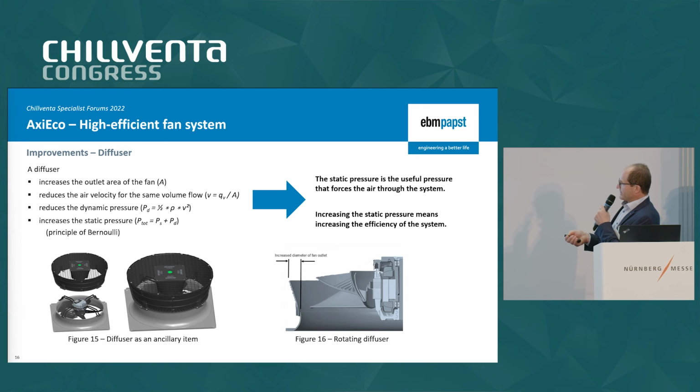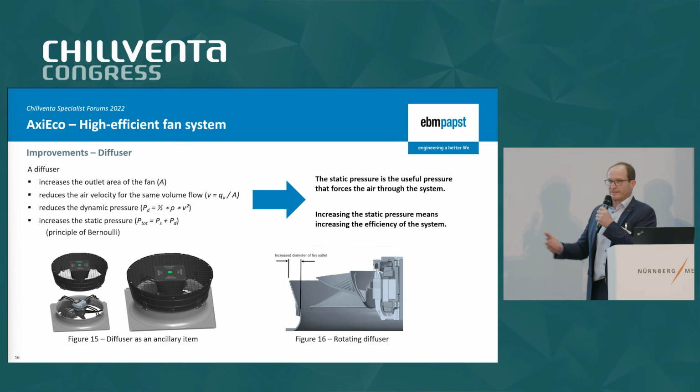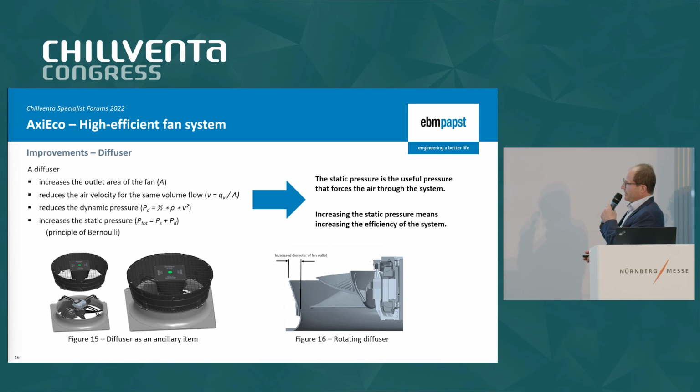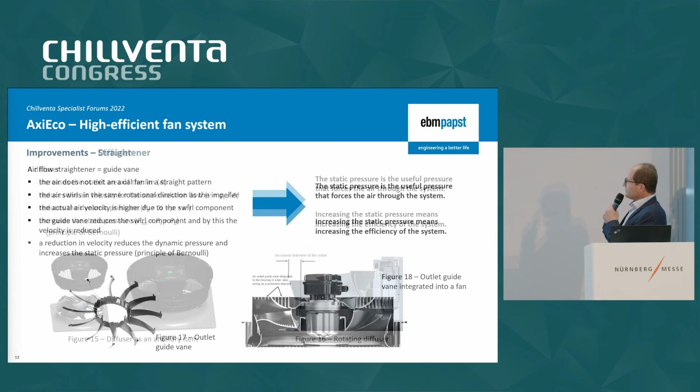So it's not just a simple wall ring, it's a conus. And this acts like a diffuser because we have a larger air outlet area compared to the air inlet area.